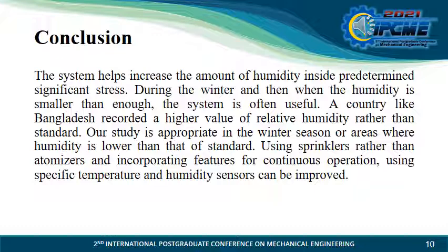Our study is appropriate in the winter season or areas where humidity is lower than standard. It can be improved by using sprinklers rather than atomizers and incorporating features for continuous operation using specific temperature and humidity sensors.